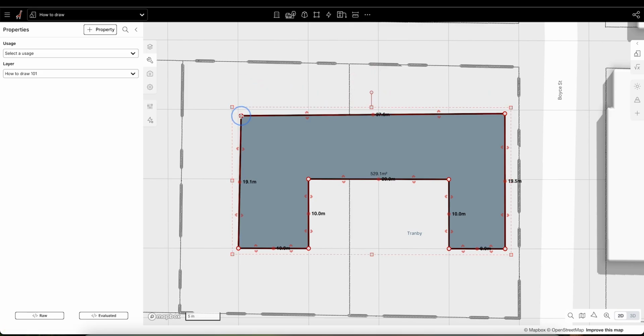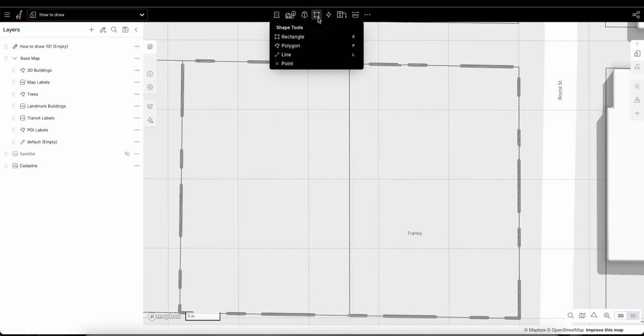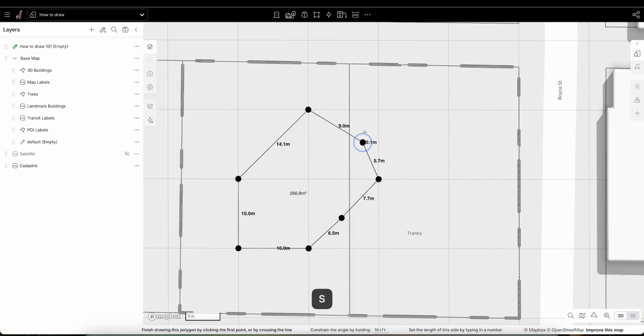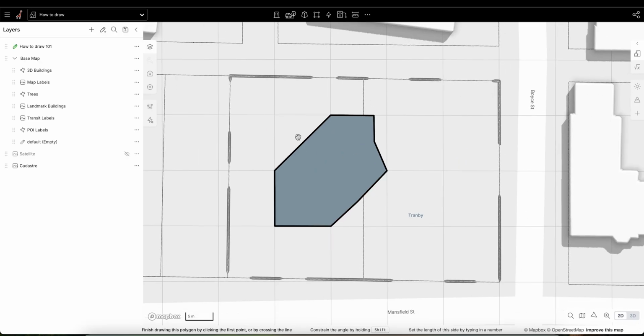And so if I drag that down, what I can do is hold Shift, and you'll notice that it snaps to 90 degrees in those two angles. And so we get back to that rectilinear form where I started. So let's remove that one. You can obviously be quite liberal with the polygon tool as well. I drew it in a more controlled manner, but if I jump in here to polygon, which is P on your keyboard as well, I could start to draw something quite creative and abstract if that was my intention. So you can just as easily create geometry like that as well.